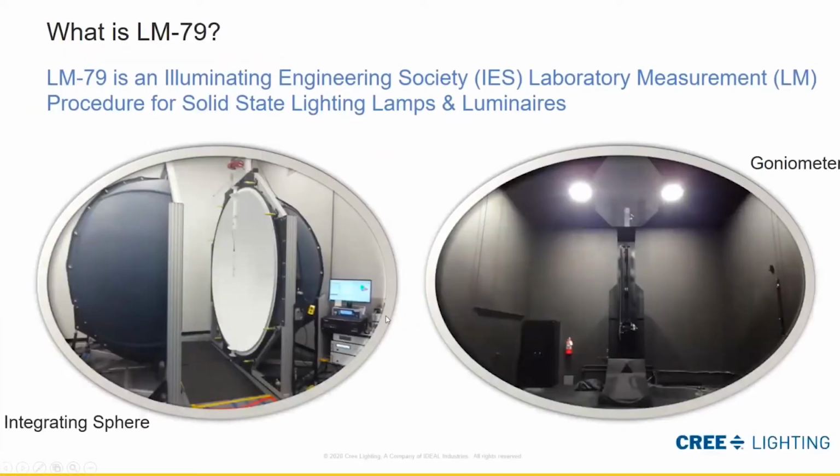All right, so today we're going to talk about the LM-79 report, which has become ubiquitous with a photometry report, but in particular, it's actually only applied to solid-state lighting lamps and luminaires. This is a laboratory measurement specification that is generated by the Illuminating Engineering Society, and I happen to sit on the test procedures committee, write this and update it as industry needs.